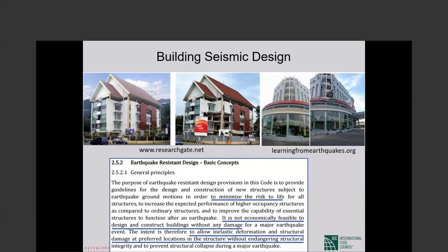And after this earthquake, they don't believe us that we design according to code, because they thought that if your building is a new building according to the new code, it shouldn't get damaged. But really, we are designing for damage. The way that we design, we expect this kind of damages.